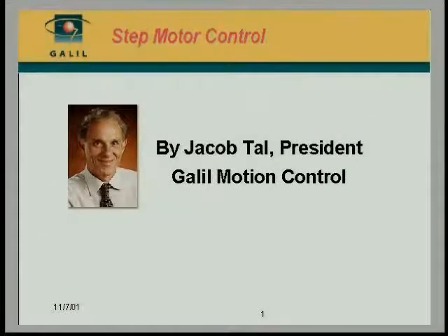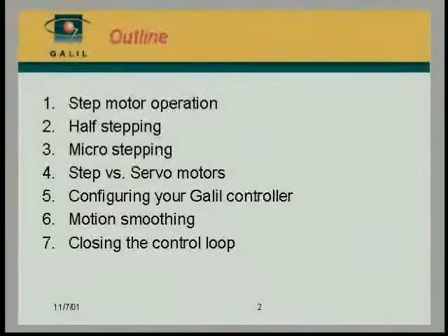The subjects we'll cover include first the operation of step motors, and we'll talk about different driving methods such as the full step, half step, and microstepping. We'll also consider the merits of steppers in comparison to servo motors. And later we'll move on into the specific discussion of using steppers with Galil controllers. We'll talk about the configuration, the feature of smoothing, the pulse rate, and the method of closing the loop.